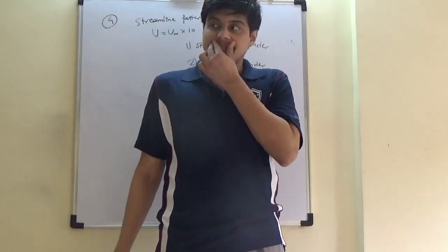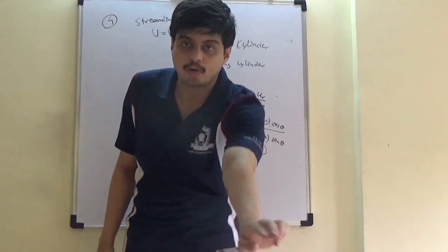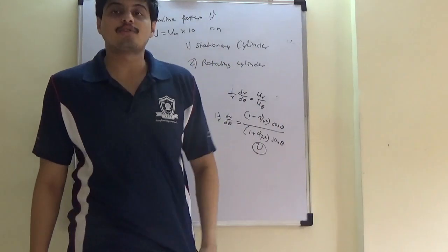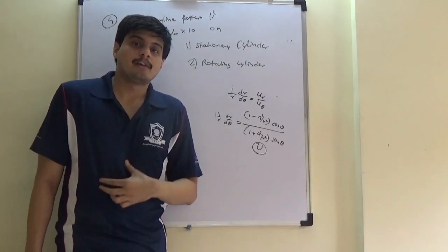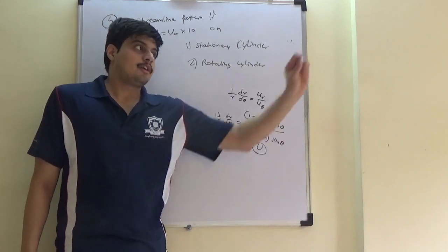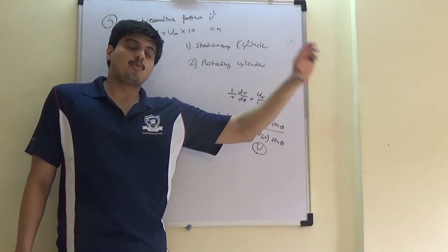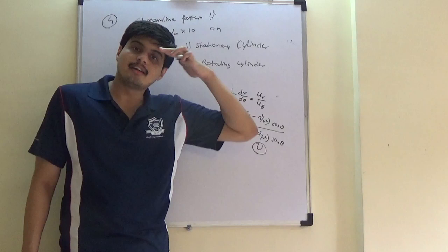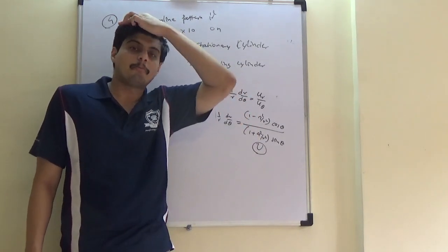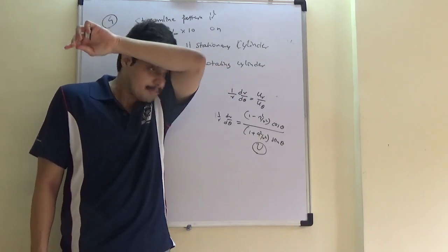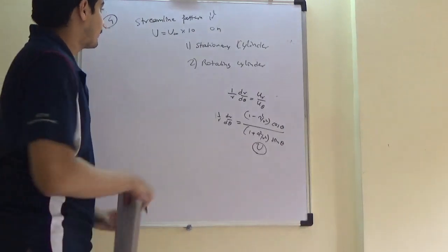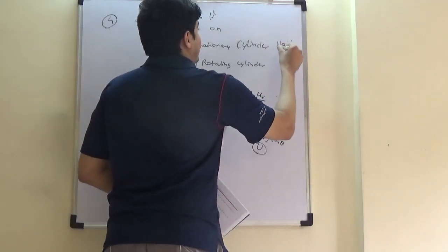Just by moving faster, the pattern of pressure drop on the cylinder because of the symmetry is not going to change. So the streamline equation remains the same. You move at 20, 200 or 2 meters per second. The photograph of streamlines, the lines formed by tracking the particles following a specific path, would be identical. So no impact.